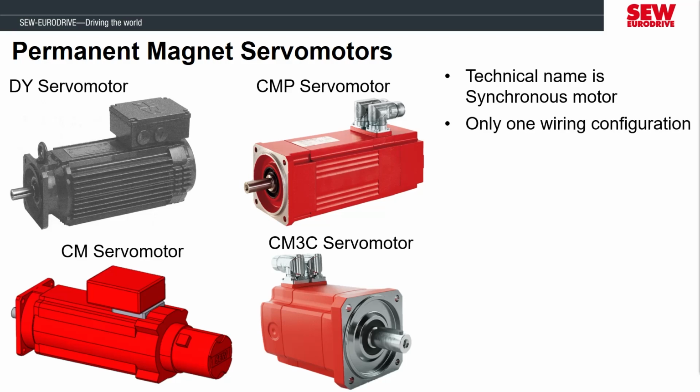The servo will only come with one wiring configuration on the terminal block, and it shouldn't be changed because it can cause the motor to have erratic behavior. This means it has to be ordered for the correct inverter voltage. A 230 volt servo will have a different stator than the 400 volt version, so this can't be changed in the field by rewiring.